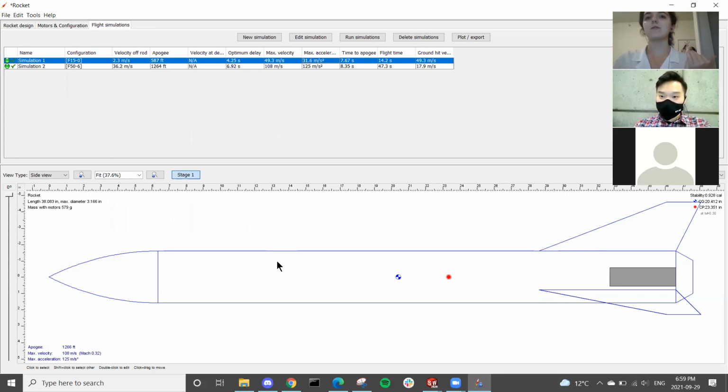Sometimes it's really hard to avoid because you need to put so much mass to get your minimum allowable CG, and then the rocket burns off so much that the CG moves way up to the front and it's hard to control your center of pressure. So things can happen, but it's ideal to keep it below 6.